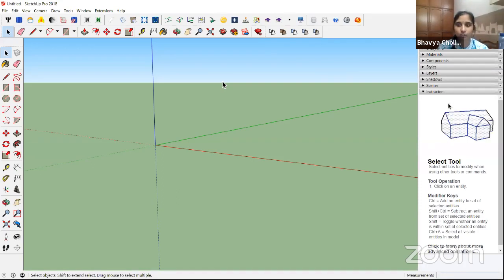See, I would say SketchUp is accurate, it gives you accurate analysis because we consider the exact geolocation of the site based upon our requirements. When you're working with many considerations, like if I have my own building, then I'll have that respective location exactly, and you can add that location into SketchUp so that it will give you a clear-cut shadow analysis based upon your location criteria. So that's how I can assure you that SketchUp will give you a good and accurate analysis based upon your requirements.